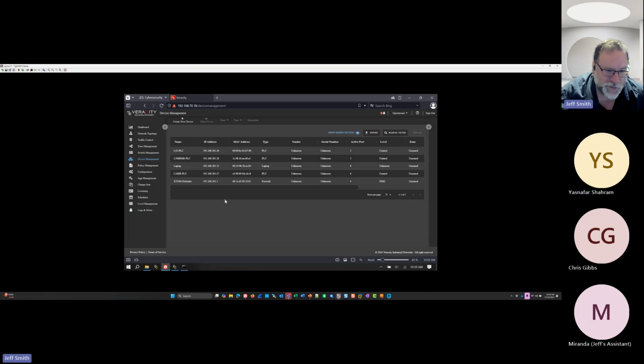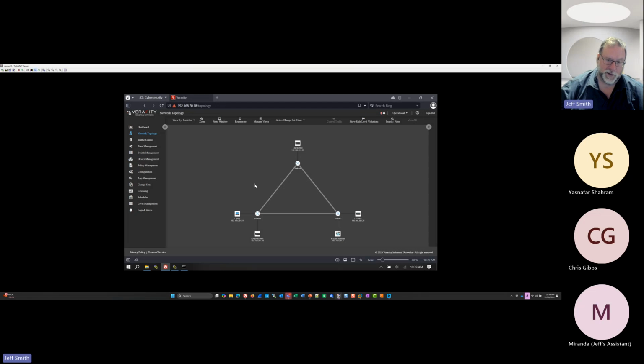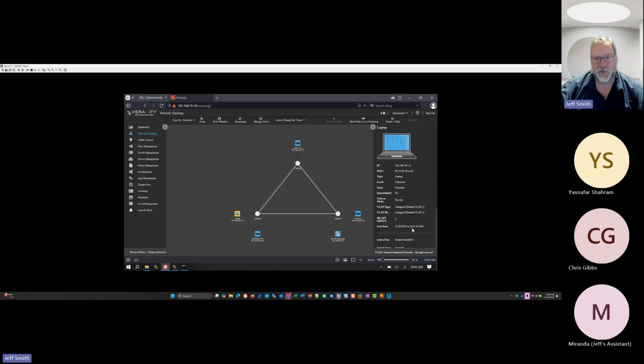So you can use other third-party tools to grab data from the system. You can manage policy, switches, zones. I tell people it takes me about 15 minutes to show you how to manage your network, and that's completely different than anything anybody's ever used on the plant floor. If a controls engineer wants to let something new on the network, it's either got a policy that already covers it, depending on how broad the policies are, or they can literally come in here. They'll plug their new widget in, it'll show up, they can click their widget, click where they want it to talk to, and say allow it over Ethernet IP, and it's done. So it's very easy to keep the network secure. It's very easy to manage the network. It's not a full-time job.